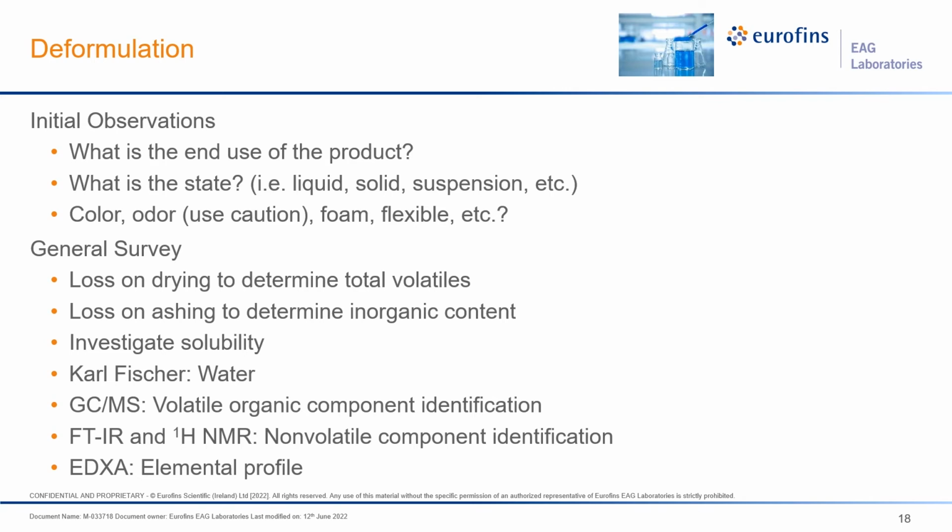Loss on drying to determine the amount of volatiles in the material. We evaporated the adhesive. What was left? Loss on ashing to determine inorganic content. We ashed the material to see what inorganic components were still there, how much inorganic material.